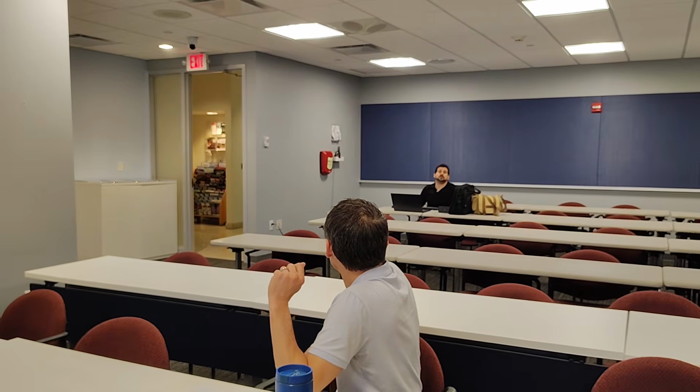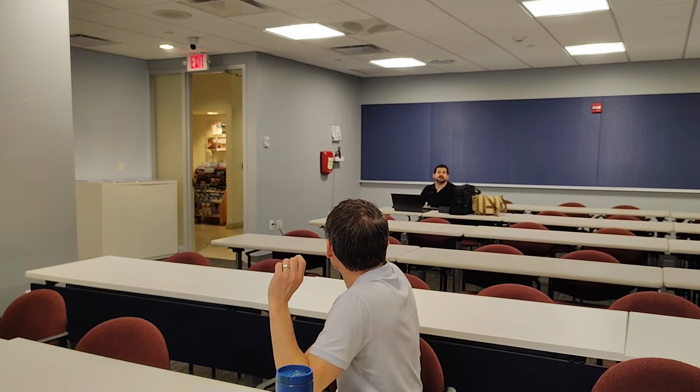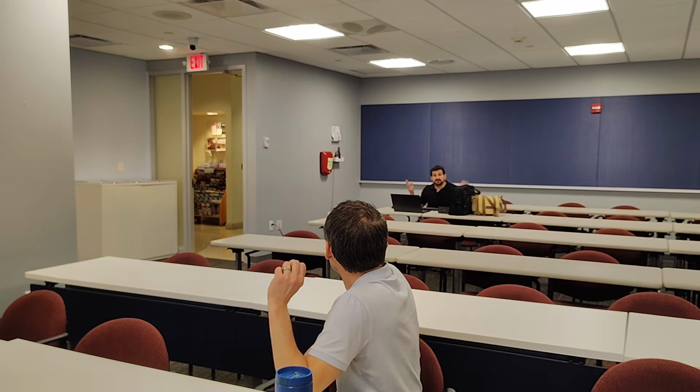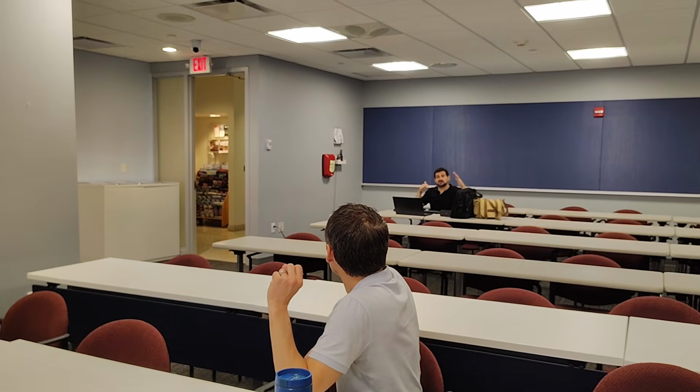Say it's 79 degrees in my office. Then the question would be, what's her set point? And if her set point is lower than 79, then it doesn't matter what you do, because that VAV is not doing what it's supposed to do. And we wouldn't be able to change that. Right? But if the set point is 79 and the space is 79, well, it's not going to open. And then if you were to change that set point to 76, then it would open.